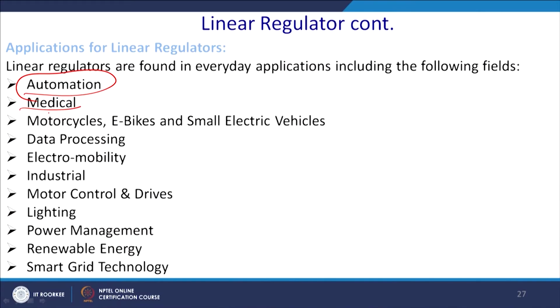There you require a very regulated power supply and you do not want switching. Switching will give you EMI and EMC problems, and that is not possible to use, and it will be hazardous to the patient. So, in that kind of application, where we are monitoring any voltage or current, or pulse speed, or amplifying, this IC regulator is preferred.